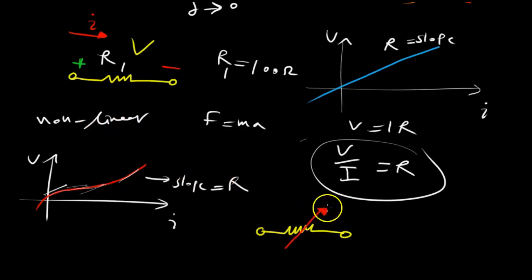That arrow usually means a variable, meaning it's not constant, you can vary it. It can be useful in tuning instruments and things like that. You can vary the resistance, for example, between 10 ohms and 500 ohms, and with that you control the voltage drop across the resistor and the current through it, which can be useful in some applications.